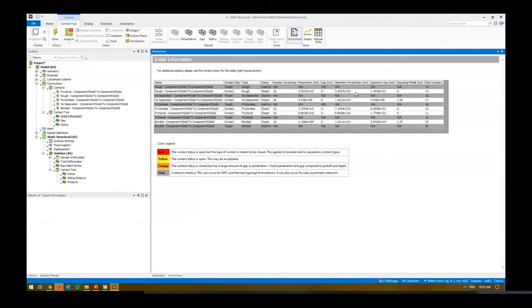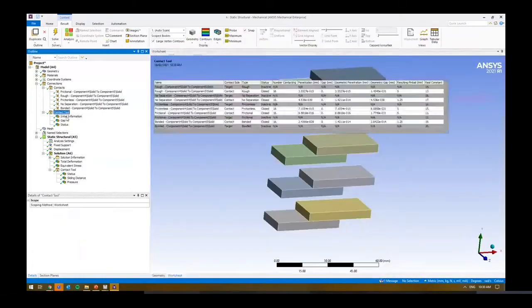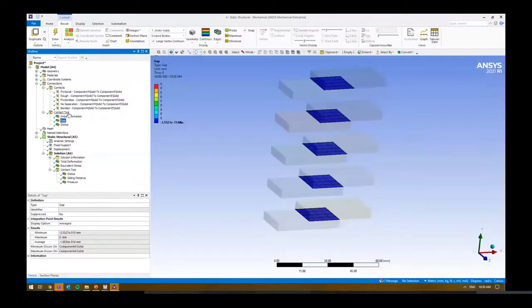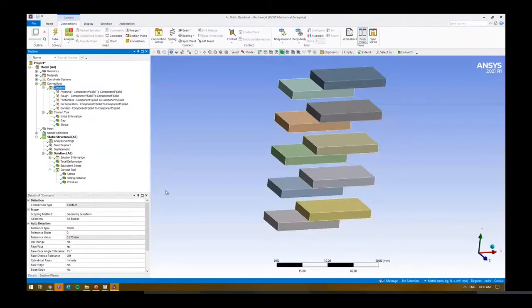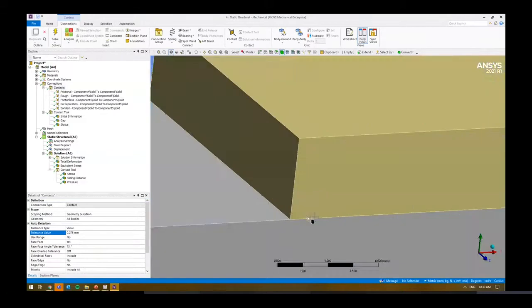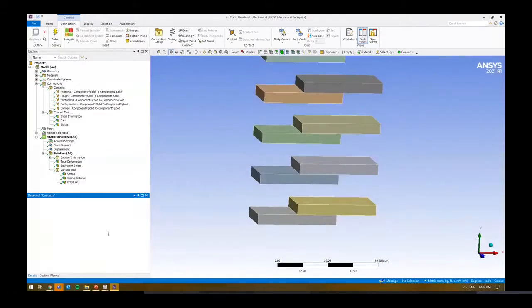So if we've got a frictionless contact, something's coming into contact, we might have a gap, and we can see the resulting pinball as well. Now, you'll notice again, we've got the gap. We can also right click and easily show what's happening around some of these regions. The reason this information is important is sometimes, when you've got large geometries, the values might be very large, right? So instead of looking within a 2 millimeter radius, maybe it's looking in a larger one, right?